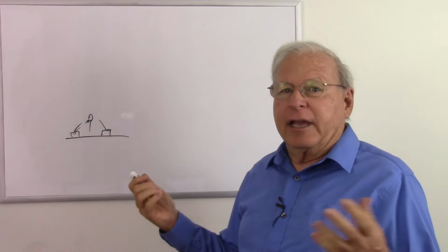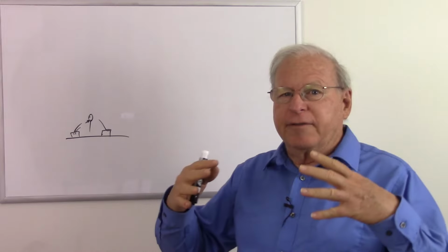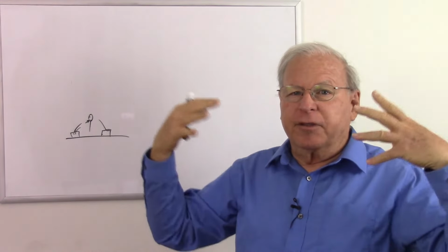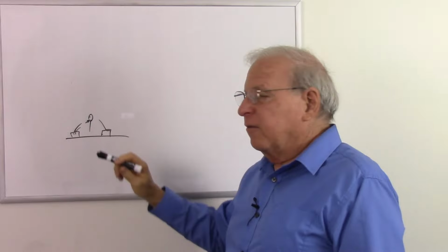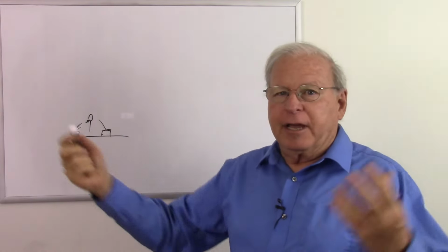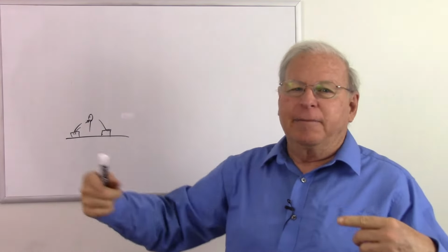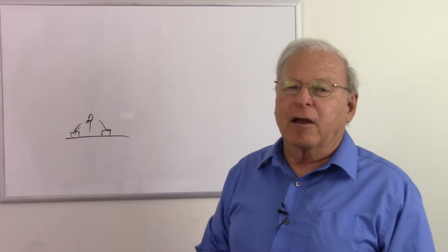And also, like in churches and auditoriums, you're going to have that problem with feedback coming from the speakers, which are pointed at everybody. So if you have a cardioid microphone, it's going to tend not to pick up those sounds and therefore not repeat them and cause feedback or feedback oscillations.